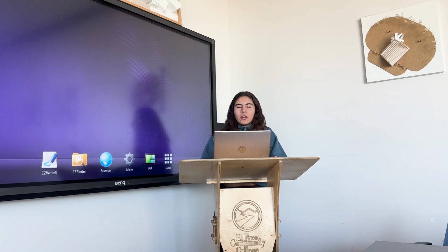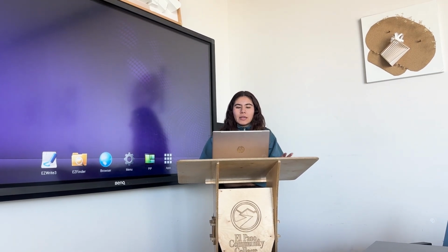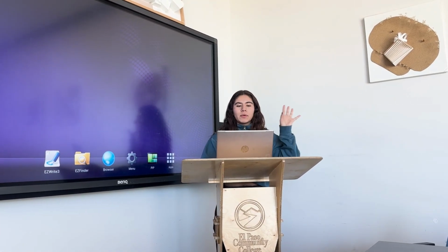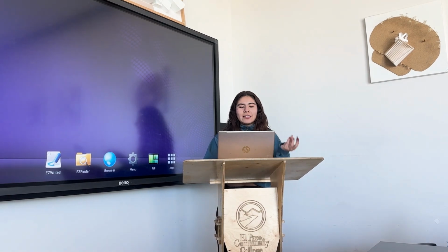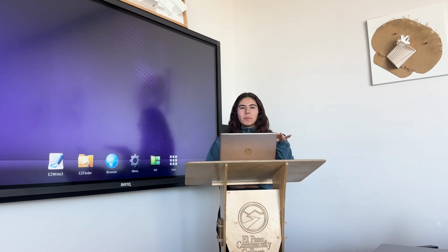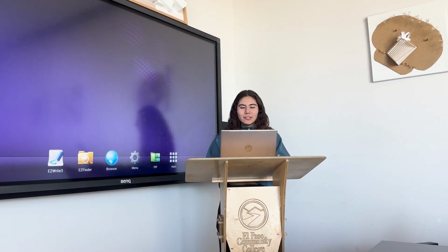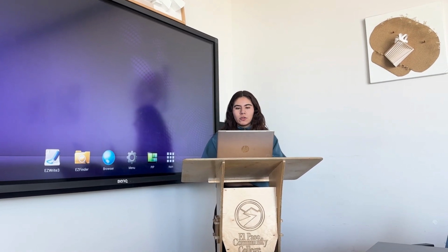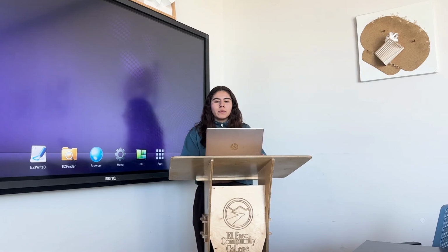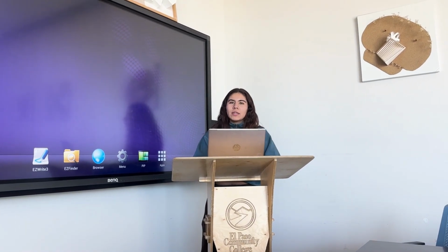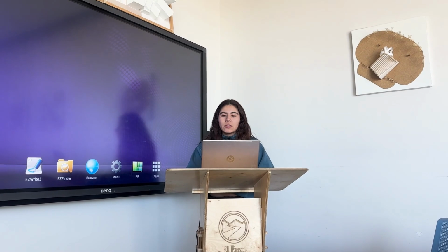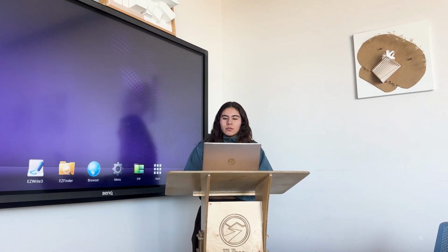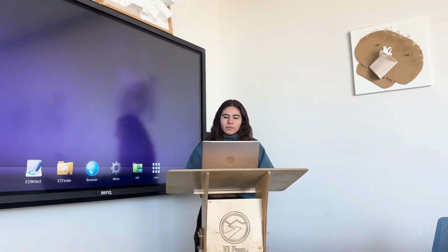So this provides enough space for the masons to keep the cavity free of mortar obstructions while the wall is being built. Where insulation is inserted into the cavity, the remaining clear space within the cavity is maintained at a depth of at least 1 inch, 25 millimeters. Or if alternative provisions are made to ensure adequate cavity drainage, such as insertion of a continuous drainage mat behind the veneer, the depth of the clear space may be reduced further.